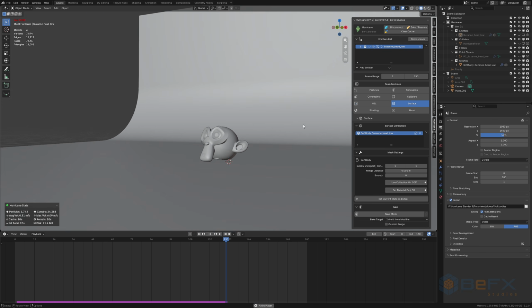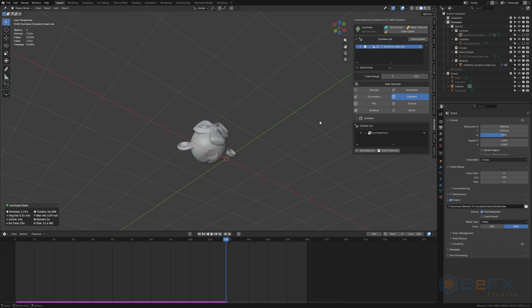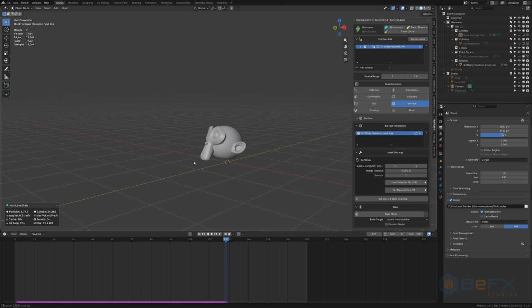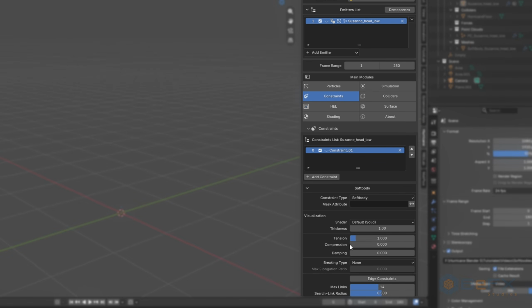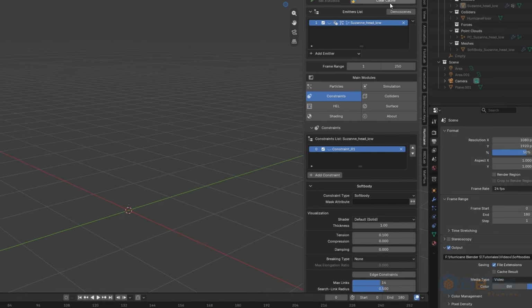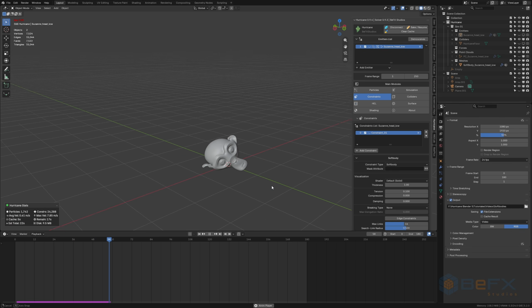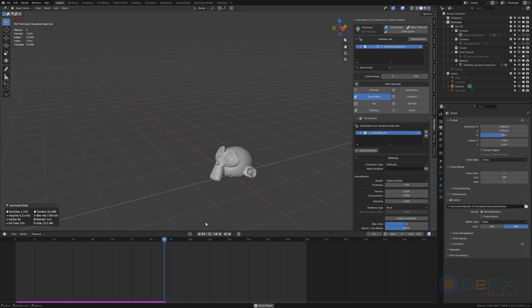We can already appreciate how the object deforms, though we notice a small localized pinch or crevice on the bottom area. We can mitigate this detail by enabling Mesh Smooth, but the ideal approach is to address the structural behavior directly through constraints. By tweaking tension and compression values, we can achieve vastly different mechanical responses, ranging from rigid rubber to highly malleable bodies. By setting compression to 0 and keeping tension low, the mesh adopts an extremely soft consistency, behaving just like jelly.